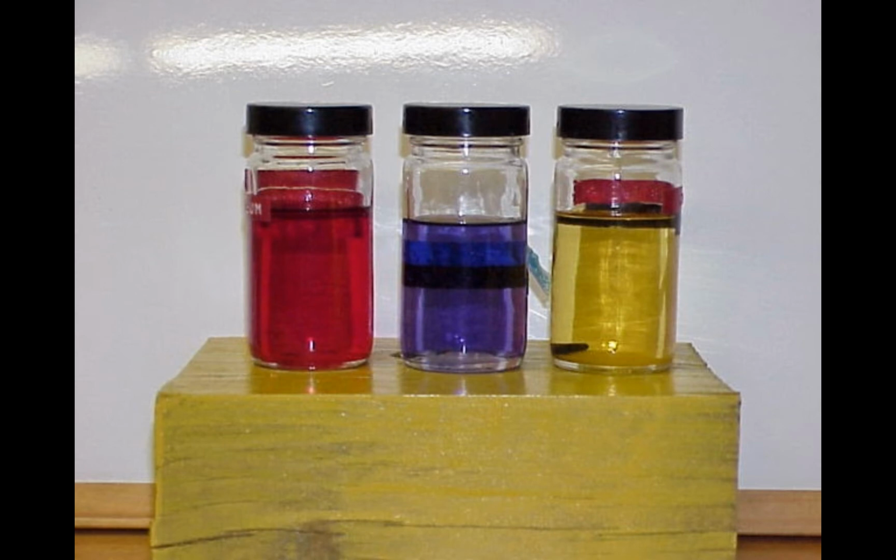What are the three principal categories of hydraulic fluid? Mineral, polyalpha-olefin, phosphate ester. Mineral 5606, polyalpha-olefin 83282, phosphate ester Skydrol. What is the color of mineral-based hydraulic fluid? Red.